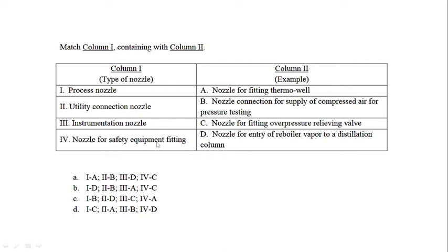Then the instrumentation nozzle can be used for fitting a thermowell. This thermowell is used for temperature measurement, and the thermocouple will be dipped in the thermowell. And the nozzle for safety equipment fitting is used for an overpressure relief valve, like a pressure safety valve.